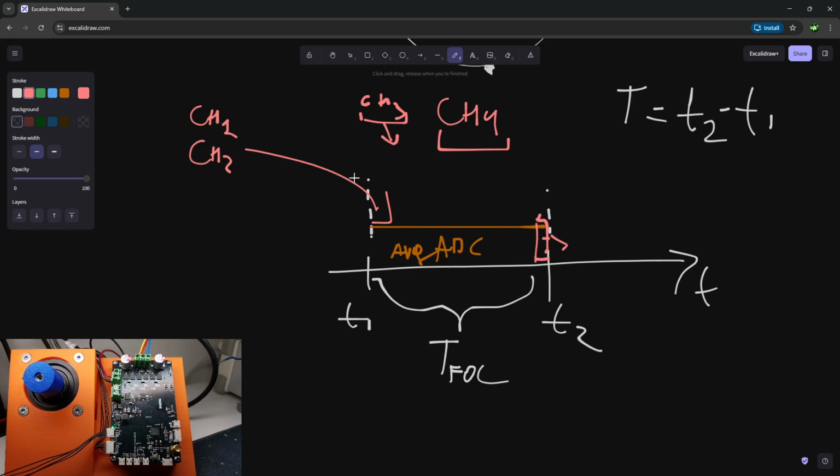And the problem is we only have two ADCs and they're both busy. So this is a problem with the MCU I've selected. The better solution would have been to have an MCU with 3 ADCs. The 2 ADCs would only work on FOC current measurements at all times, and the third ADC would measure all the unimportant channels. That would have been the best solution, but the microcontroller I selected doesn't support this. So we have what we have, and because of it, we have design shenanigans to make both work.